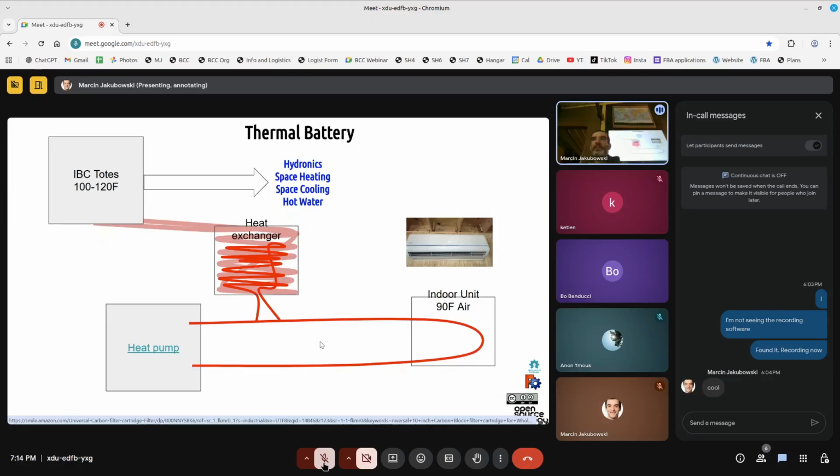So if you can dig your pipes underground like that and have enough length of it, like 1,000 feet, you have considerable cooling power just to run that directly in a heat exchanger to cool your house in the summer. But that doesn't address the humidity issue. You still have to have some dehumidification. But geothermal is basically tapping into the stable temperature.